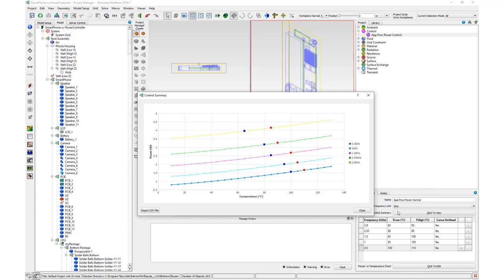The frequency is updated once every time step. For steady-state analysis, the frequency does not change. The starting frequency is used for the entire simulation. All of this data can be exported to CSV for external processing by selecting Option in the bottom left of this dialog.